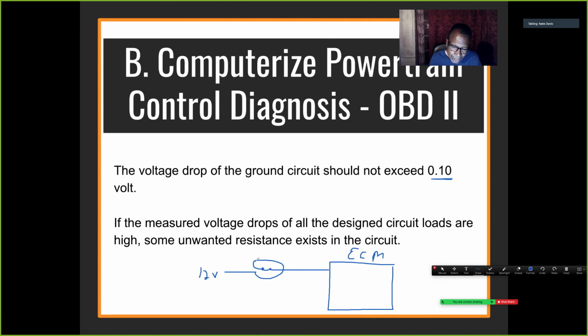If this is source voltage going to the load, then on this side, no matter what, that's the ground side. It has to be. Even though you don't see the ground symbol, if this is source voltage and that's the load, this has to be the ground side.